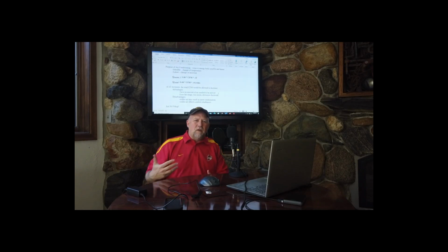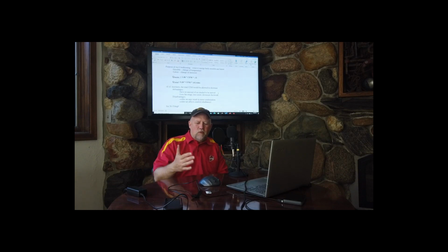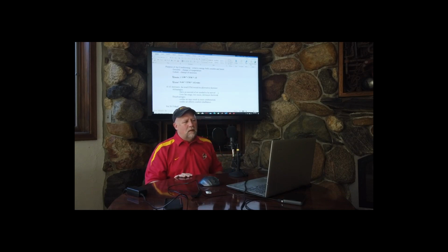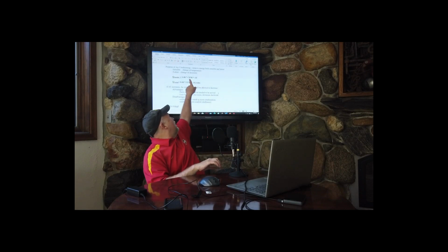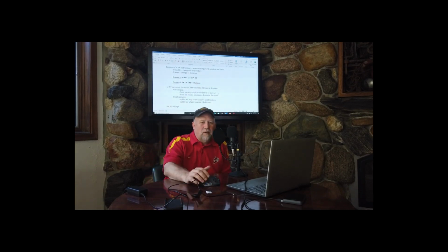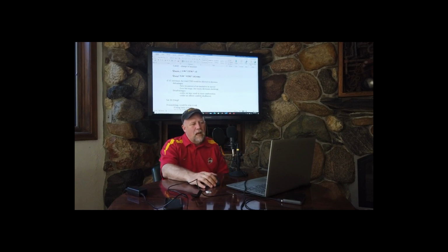That's like a remodel question. I've got this room. Let's say I want to turn it from an office space to a computer lab. Well, how many computers and how much heat production could I have based on existing equipment? All right. So measure CFM, measure delta T, and then calculate the maximum heat gain that's possible.